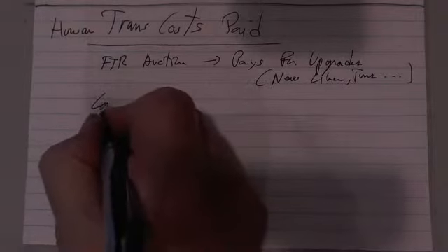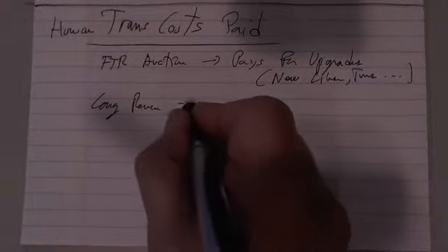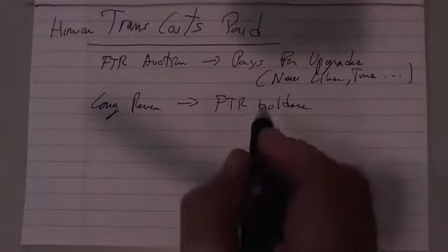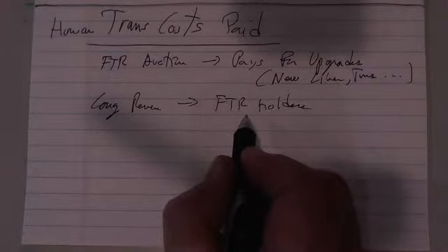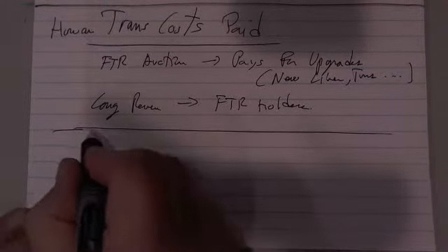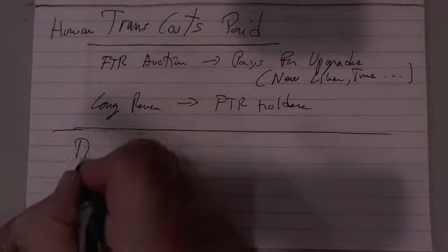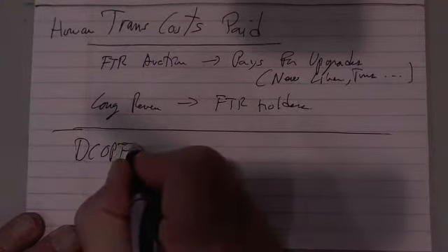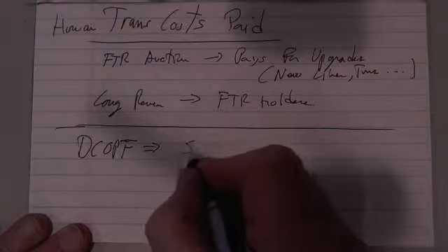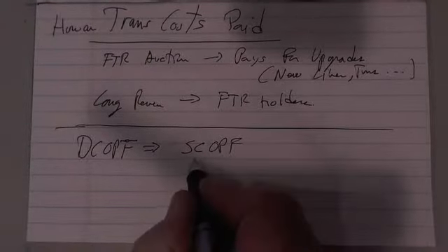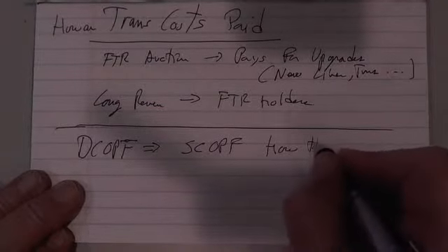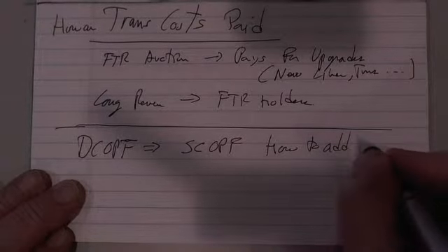And the congestion revenue we talked about goes to the FTR, what they call the holders. This is all mystery, but we'll go through that next week. Now I asked him another question. I said, if we use DC OPF, now, why do we use DC OPF? It's fast. It solves. There's no problem in converging. I can do security constrained OPF by adding security constraints. Well, then how to add losses?